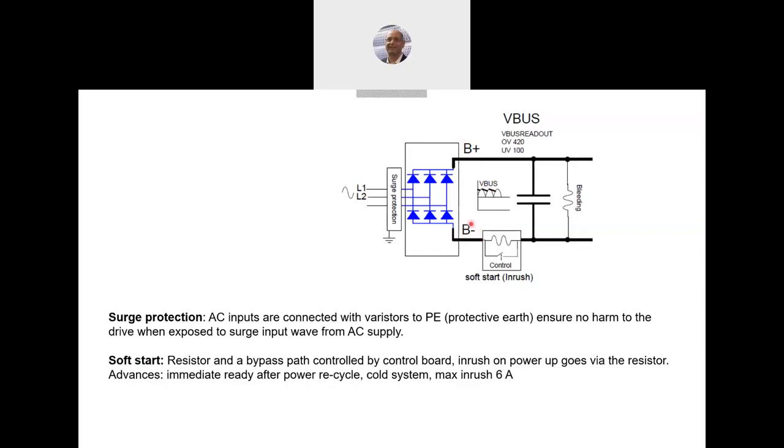Now, since I don't see you and we are not next to each other, I will ask the question, and for today I will also answer my question. So the first question is, how does a capacitor behave when it's empty? Usually a capacitor when it's empty is like a short. So if I don't do anything, I will get an inrush of 2, 3, or 5,000 amps.